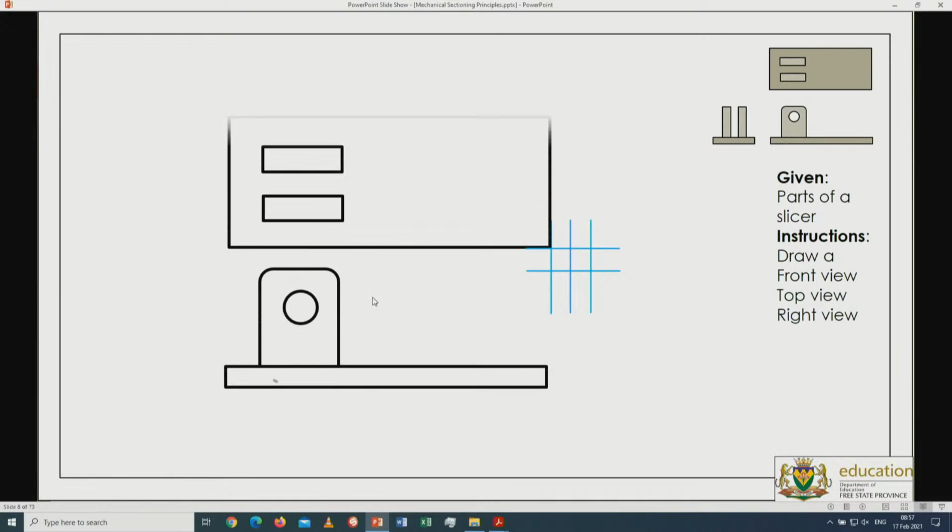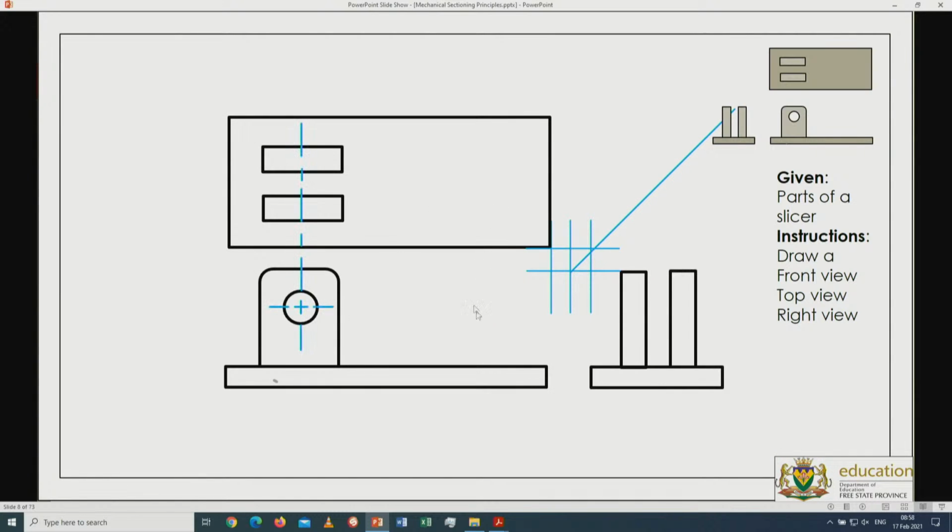And now I can shift my drawings in position so that this distance from there to there will be equal to the distance from there towards that point. The distance from the top of the page to the top view, and the distance from the bottom of the page towards the front view, will be equal, since I've worked out this system perfectly.